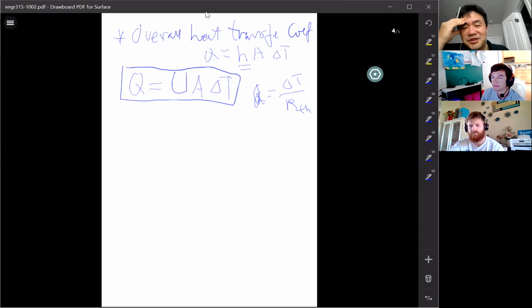It's related to the geometry, right? It might lead to a mistake. So some engineers like to use the total area, so there's only one area in this calculation. Let's move the area out of the thermal resistance calculation, because otherwise the problem is you have many areas, right? Every item actually has a different area.